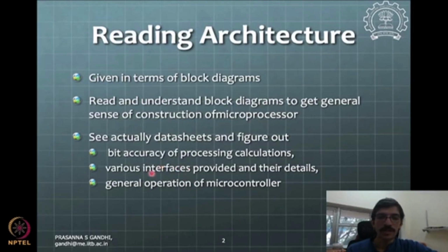So for example, in terms of interfaces, the 8085 will not have any interfaces provided. It will have just some ports available as parallel ports or serial ports and things like that. And then one has to interface some additional peripheral chips with this microprocessor to make it a microcontroller. So that is the basic difference, to make it a hardware interface for exchange of data.